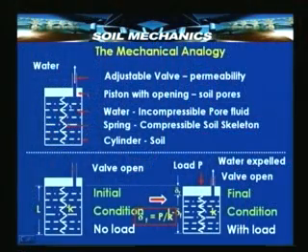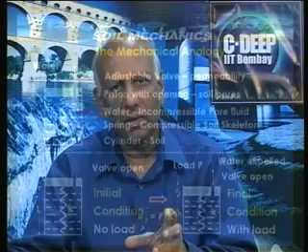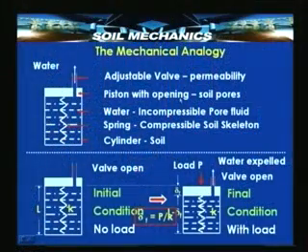Then this water which is here, as I said, not only represents the equivalent of saturated clay, but it also is helping us to simulate the incompressible part of the skeleton, that is the pore fluid. Then we have this piston which is nothing but an arrangement through which load can be applied to this soil, and there is a hole in the piston which in fact represents the soil pores